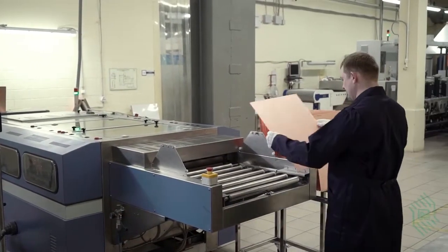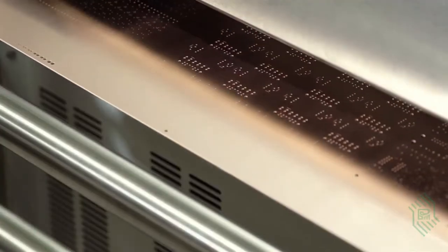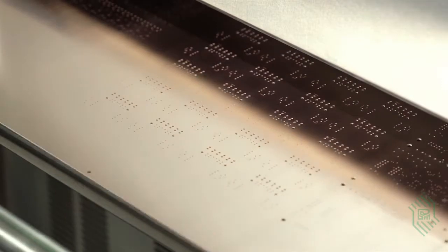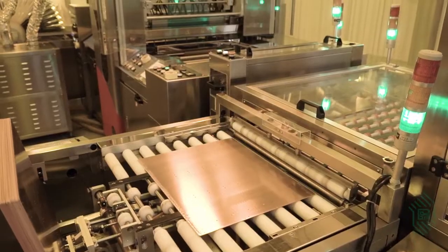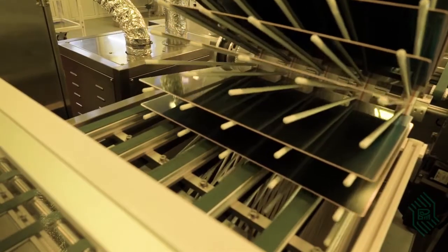In the first stage, the surface preparation equipment is used. A mechanical surface preparation using abrasive brushes for panels thicker than 0.5 millimeter is employed, while thinner panels pass through a chemical preparation line. The panels are cleaned of contaminants, and the copper surface becomes rough, which is necessary for the best adhesion of the photoresist. The photoresist is applied on the automated lamination line. The panels are gathered into a cassette and transferred to the imaging area.